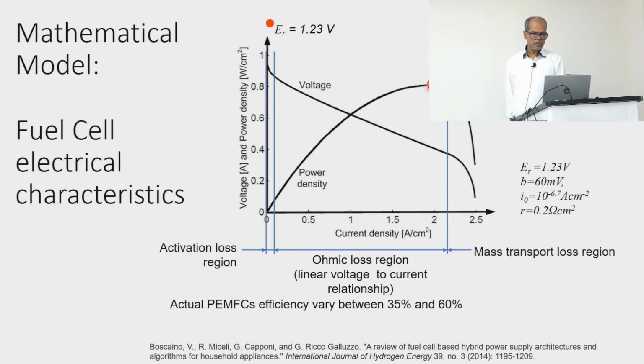But in many cases, what we do is make some changes in the voltage and see whether power is either increasing or decreasing. For example, if it is here and you make changes, it's going to increase. But after going past the maximum, if it changes, it's going to be reducing. So that change is either positive or negative. That's how you can find the maximum. But there are many ways, and recently people are even using AI and very advanced control techniques for MPPT control as well.